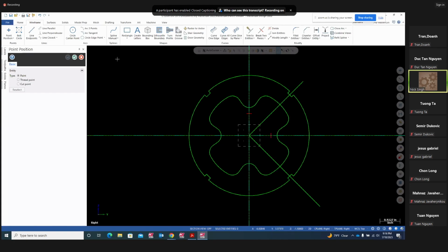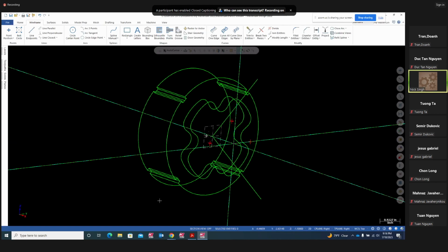This is going to be right here, point. So we're going to go Auto Cursor. X is minus 1, comma, y is 0, comma, z is minus 0.5. That point is right here. Look at that. So we got those 3 points right here.